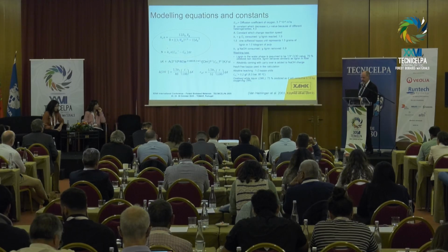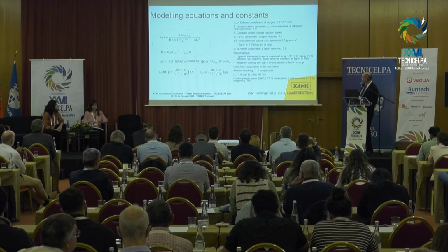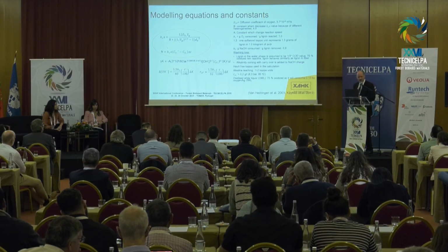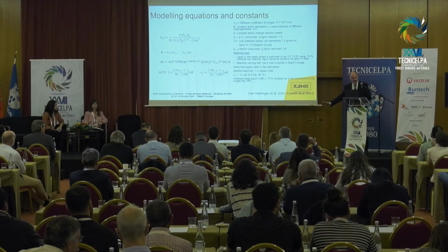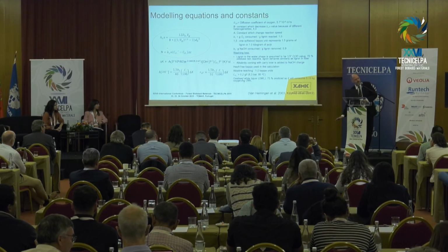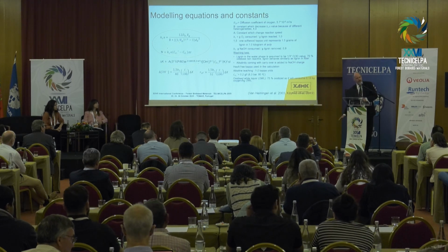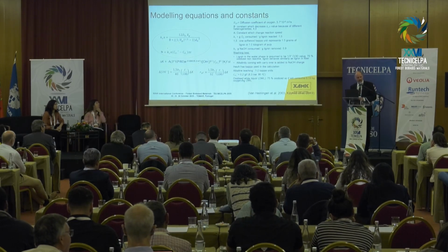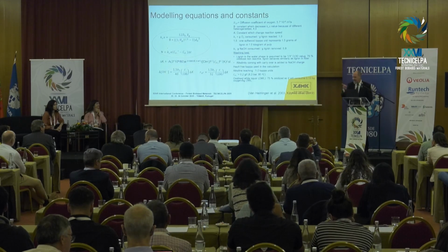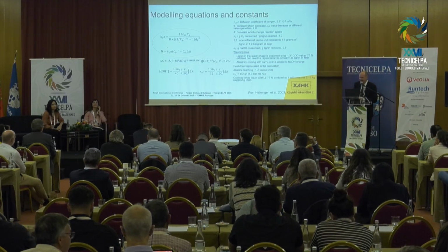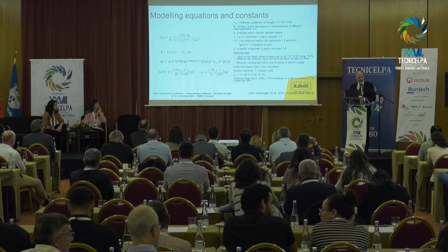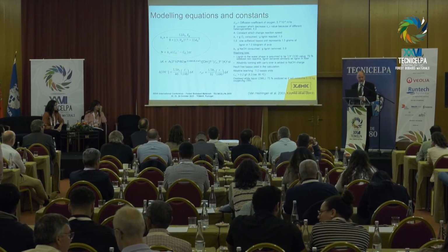One thing is very interesting here. This is the diffusion coefficient of oxygen. As you can see, this number is very, very small. So now I have a question for you. If I have a tank of water, 1 meter deep, and we have oxygen at the bottom, not at the top, only at the bottom, how long will it take for this oxygen to diffuse to the surface? Is it minutes, hours, weeks, light years, or what? Say some number. Okay, this is pretty difficult. It's nearly 1 year. So the diffusion of oxygen is a very, very slow process, and that's why we need really, really small bubbles in the process.